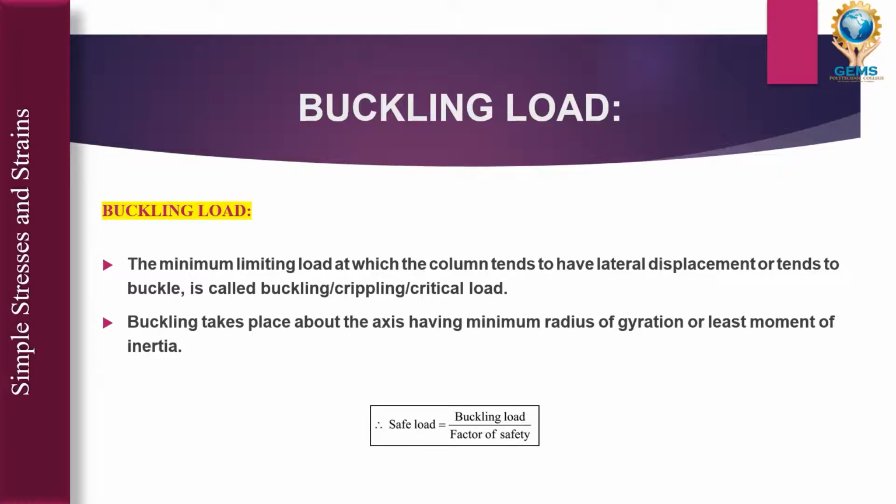So what is safe load? Safe load is equal to buckling load divided by factor of safety. Understand? This formula is very important, and once you write the correct formula, at least you will get 50% of your marks. So you must know what is safe load. Buckling load divided by factor of safety.